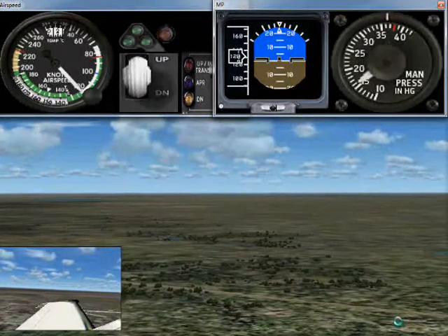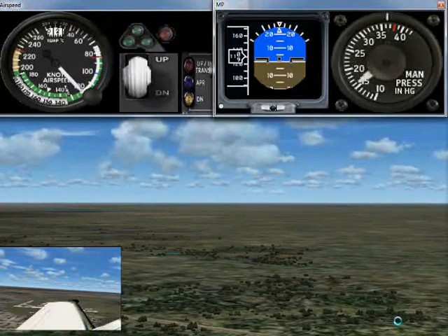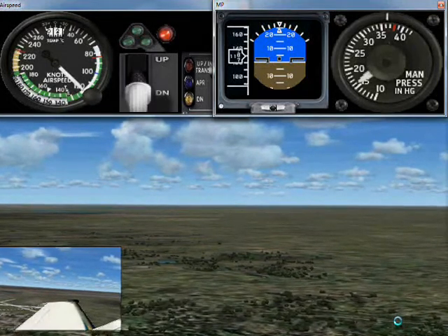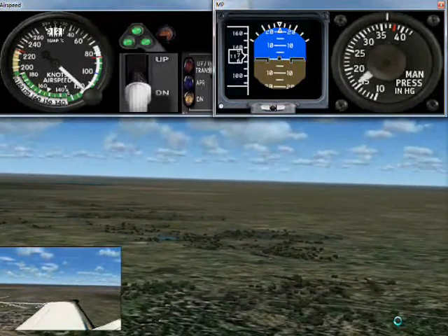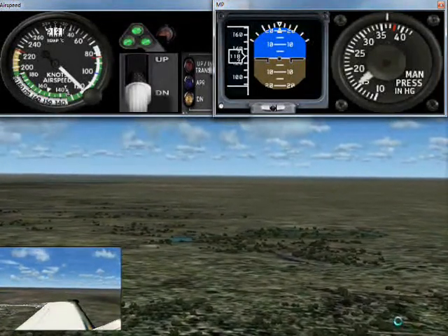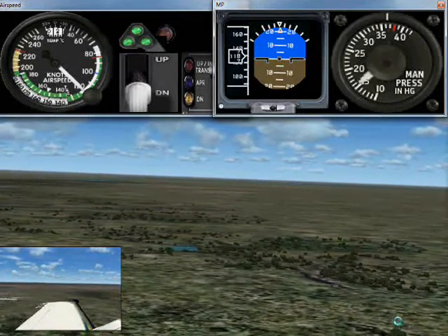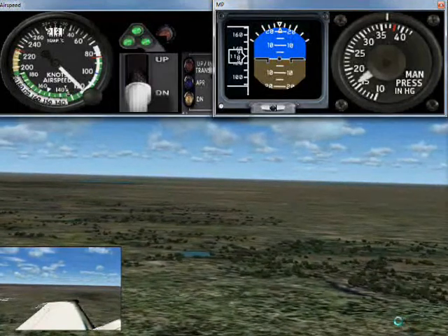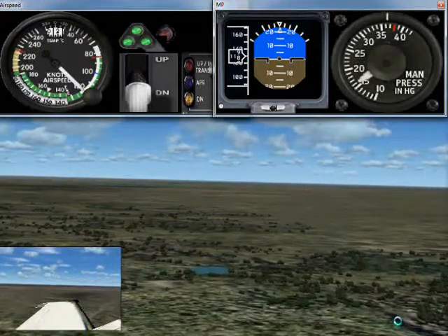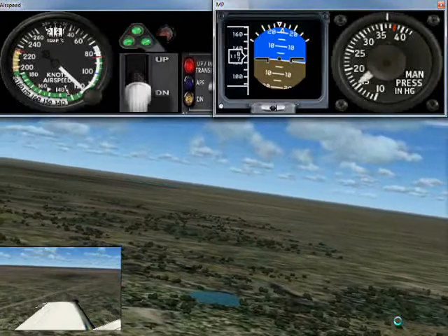We are now in level flight on downwind leg. The small window shows a view of the runway off the left wing. Opposite our touchdown point, gear down is selected and pitch attitude is set to 0 degrees and the manifold pressure is set to 15 inches, the final approach values. Starting the turn to base leg, approach flaps are selected.